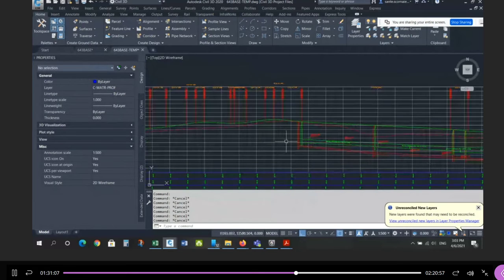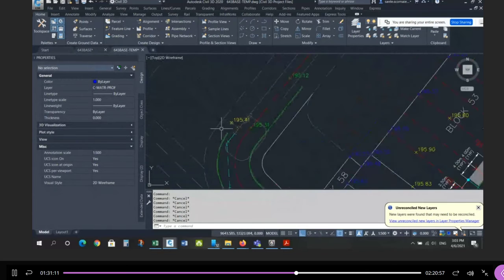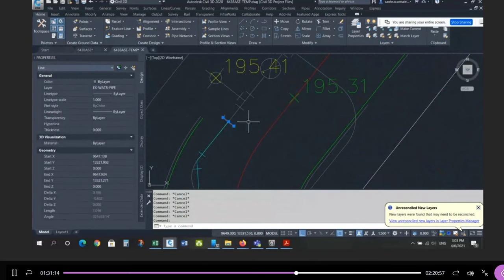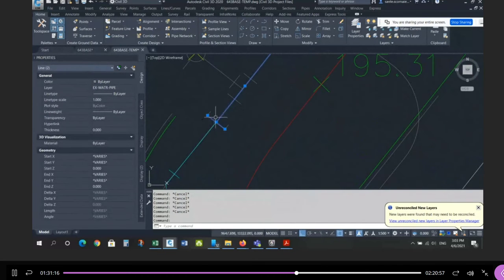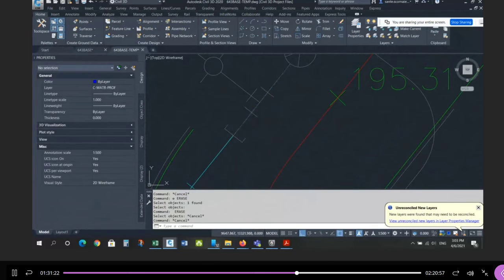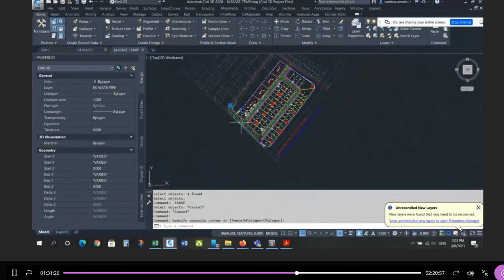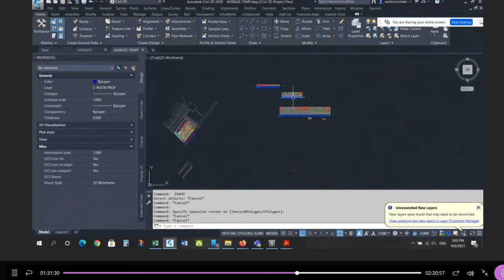Now on Chuchmak, there's an existing plug. You're actually connecting to this existing plug. So all you need to do is show maybe just a little bit of the existing pipe. You can maybe even not show the hydrant. Don't show the existing hydrant. Just draw some existing pipe and the existing plug, and then everything else inside on street B is proposed, all the way to this street A intersection.